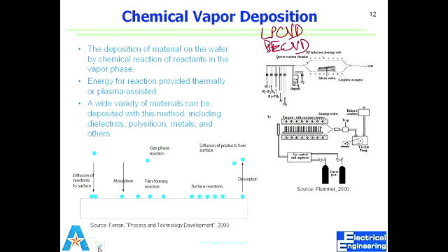Power is a very important parameter because your reaction is consuming. When your reaction occurs, you're essentially taking away the ions from that plasma. To maintain that plasma and to ionize further gas that is coming in, we need to continuously pump in RF energy, right?